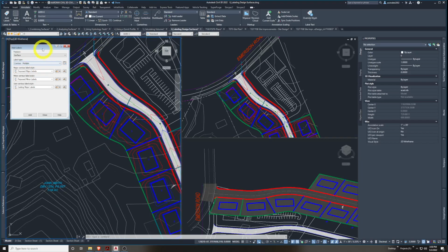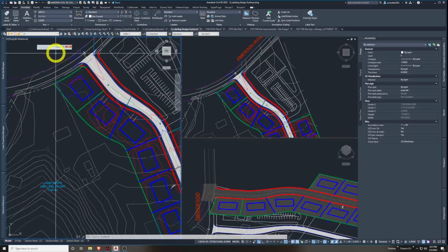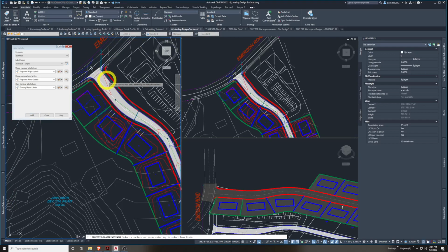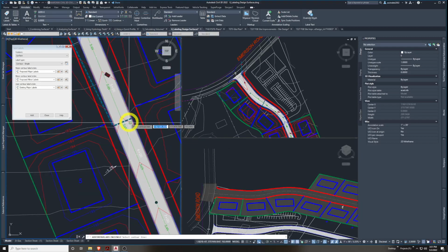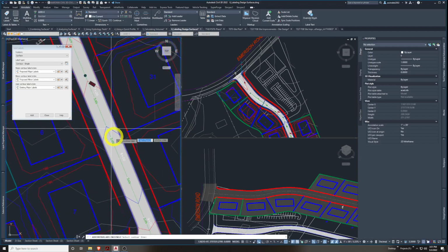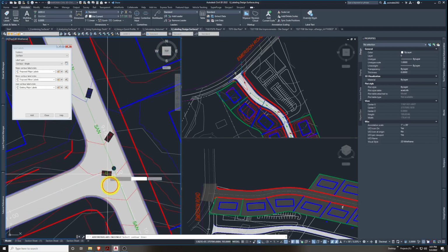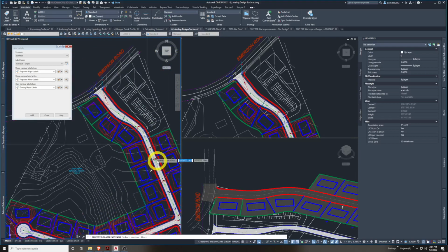Now let's go back here, leave this open. I sometimes will pin it like this, so when I move, it stays a little bit, opens up some real estate, but you can leave it unpinned. We'll do contour single. So we'll just say we want to add one contour label now. And we'll hit add. Let's pick a few contours on the Jordan Court surface. We'll add it along like this. There we go. We're just adding some contour labels in an integer format. Usually contours are in a nearest integer whole number along Jordan Court. Okay.